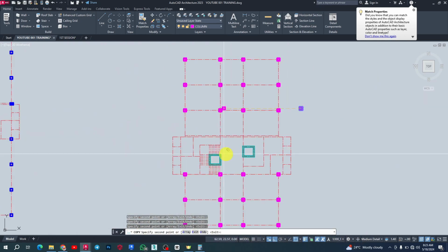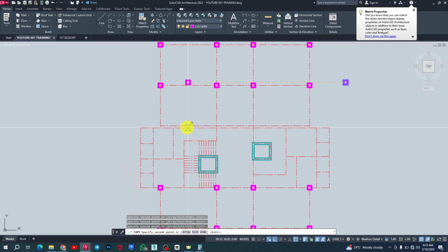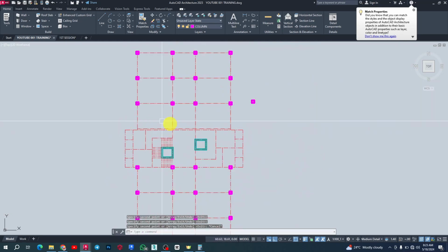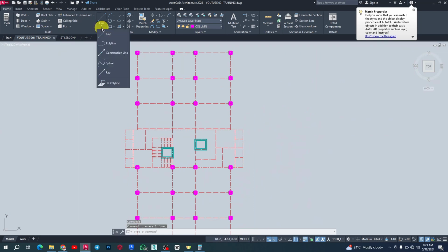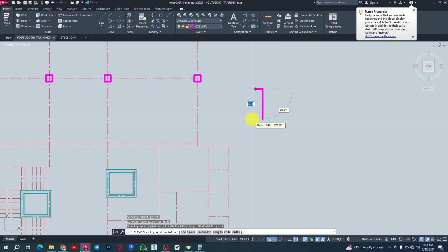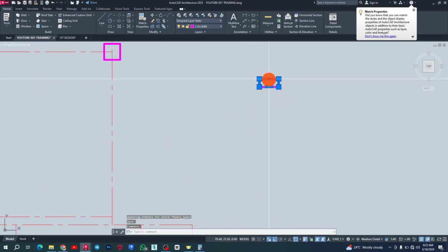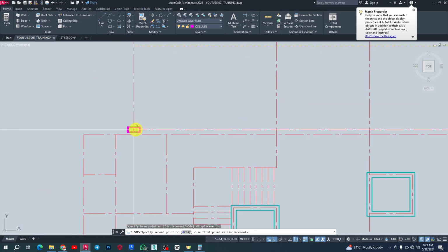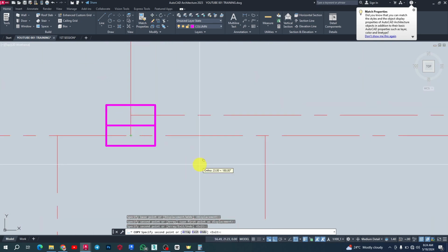We already have a shear wall along this span here, and we have 7 meters, but this expansion joint here will need another column there. So since it's a five-story structure, I'm going to go with 0.6 by 0.25, 0.6. I don't want the column to be protruding inside the rooms, right? So I'm going to take this one here, take another one here.